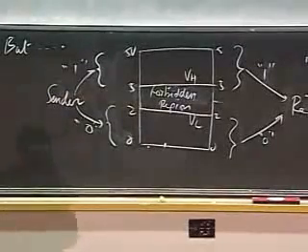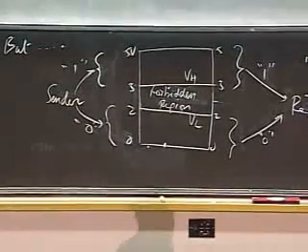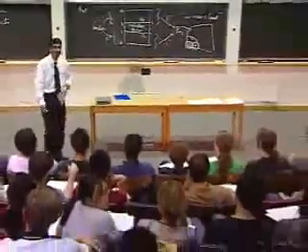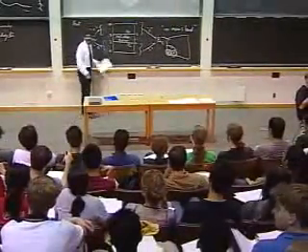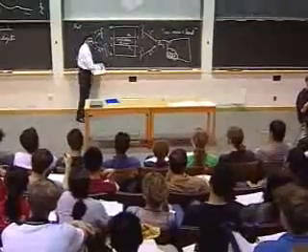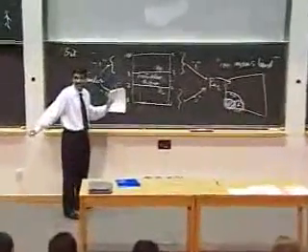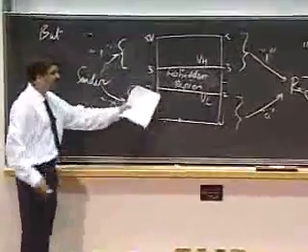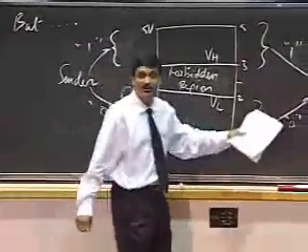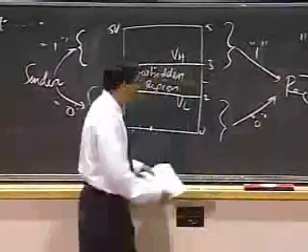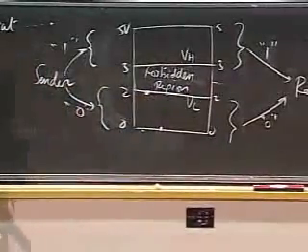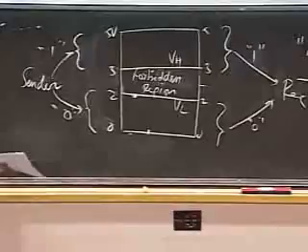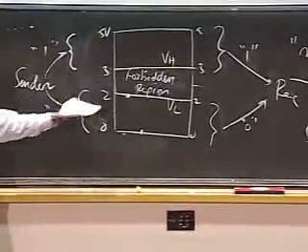Yes? If the sender sends 1.99 and noise pumps it into the forbidden region. Exactly. So what if the sender says, look, it's legitimate. I'm Intel, right? They've told me, stick to 0 and 2. And Intel parts will be sending values between 0 and 2. And Motorola parts, which are receivers, have to receive 0 and 2. So Intel can send a value of 2 volts, because it's 1.99 or 2. It's legal.